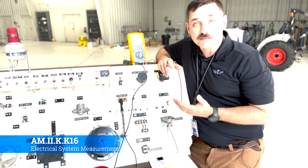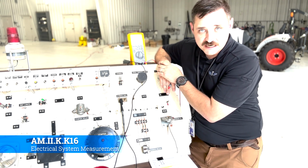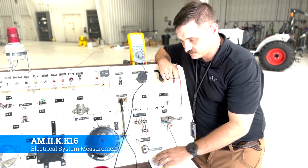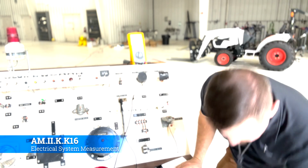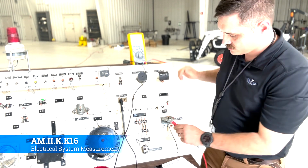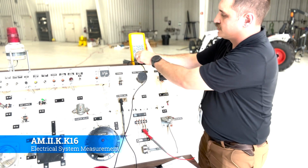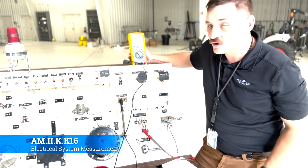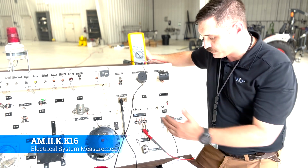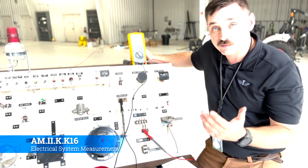This could simulate any number of things that could happen, to include broken wires, corroded connectors, disconnected components, all kinds of things that could happen to create this sort of situation. So let's go back here and we'll reset our, all right, let's put it on DC volts. Notice that there's no voltage here either. Even whenever we've gotten continuity through there, we know that power should be coming through the relay into this distribution bus and then out to the different components, and we're not seeing it.